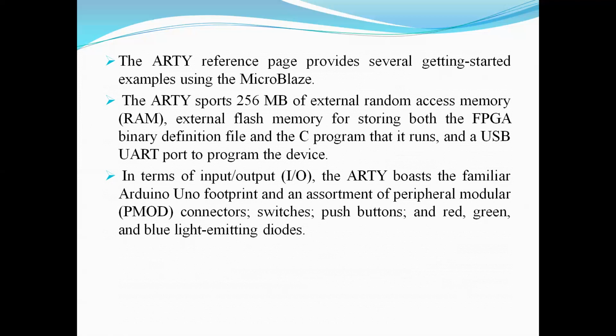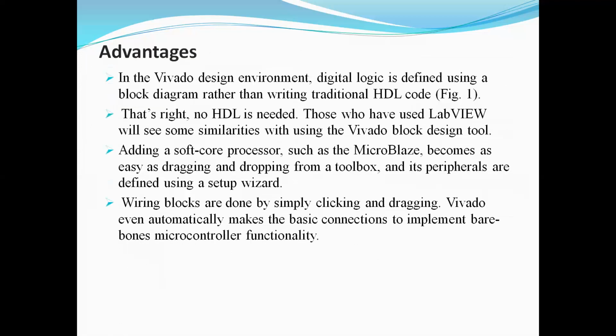Now we'll see the advantages of soft core processors. In the design environment, digital logic is defined using a block diagram rather than writing traditional HDL code. That's right, no HDL is needed. Those who have used LabVIEW will see some similarities with using the Vivado block design tool.